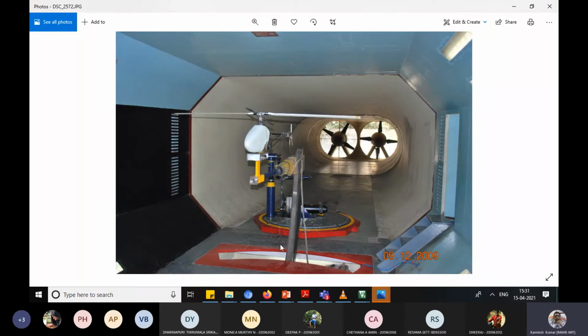So this is 9 by 14 feet, so 9 feet height and 14 feet width. This means you can go ahead with around 12 feet this much, and at least 8.5 or something. 9 feet you can't go, correct? That will hit the wind tunnel itself. So you should have clearance, like air should pass, not just hit this and go. So you should have clearance from all directions. That is one thing. And you put the aircraft as per the test cross section area of the wind tunnel.